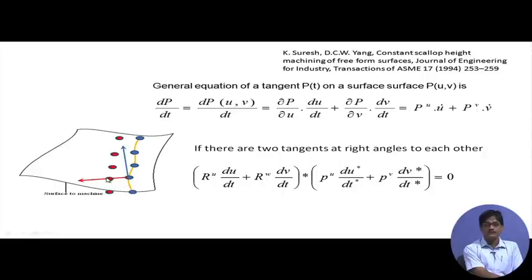For this, what we do is, we say that this particular step that we have to take is definitely going to be defined by a vector. We simply find out its direction and magnitude, which is all there is to it for a vector. So, what we say is, let us first find out in which direction we should consider the side step at this particular location of the cutter position on the first cutter path.